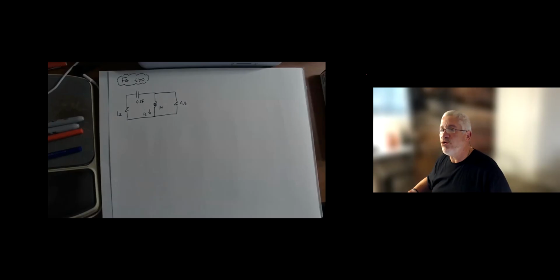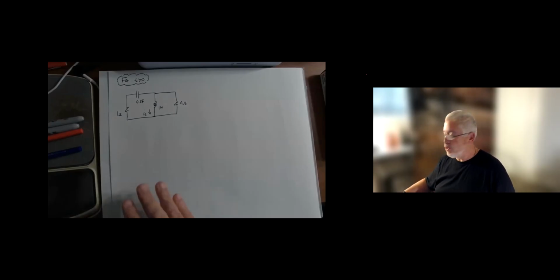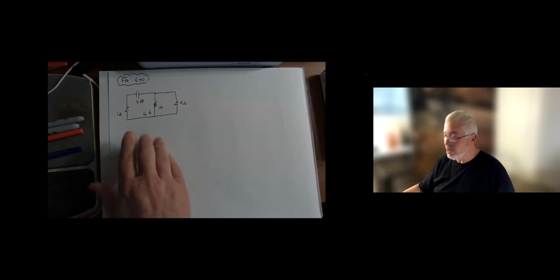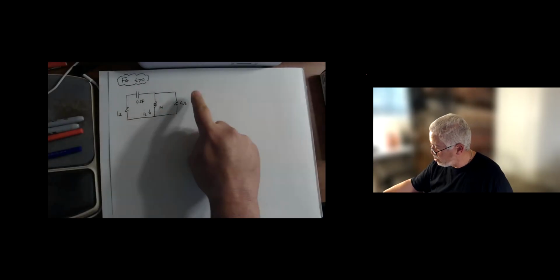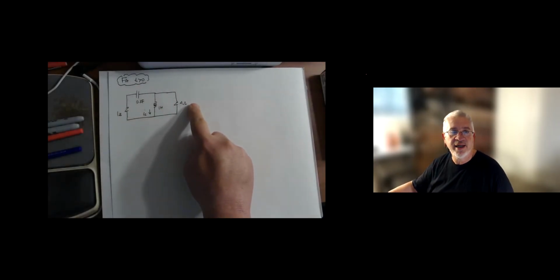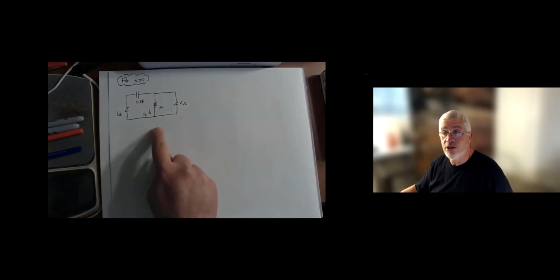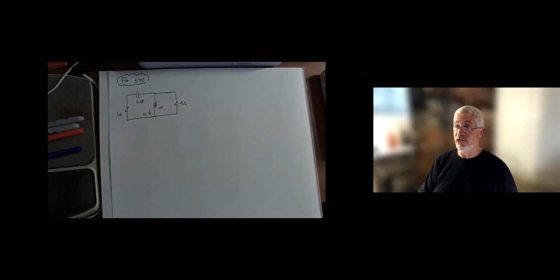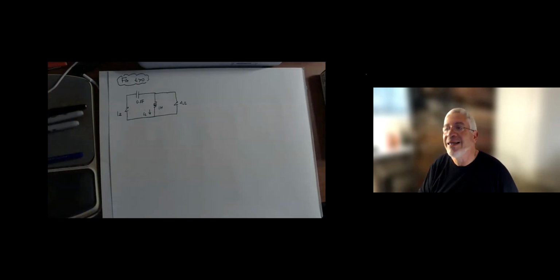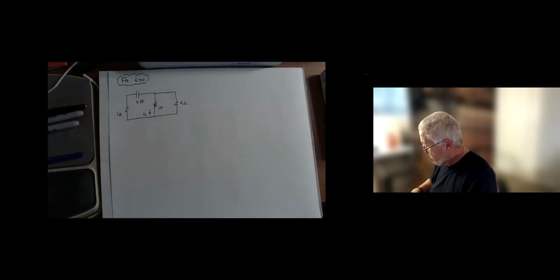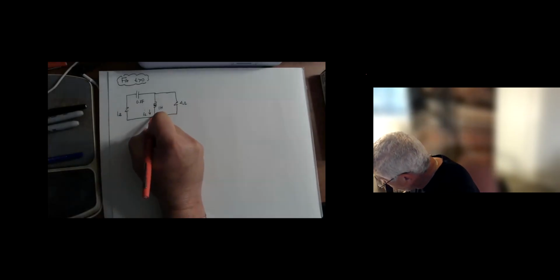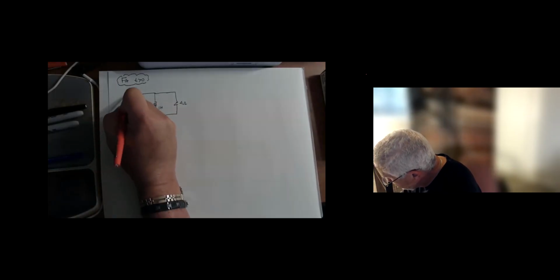But I would like you to see the nodal step-by-step procedure on how we get from this circuit, which is the circuit for t greater than 0, where the 1 amp source has been disconnected, and we have a circuit that has no source, but it has an initial condition. The initial condition is the capacitor voltage was 0 and the inductor current was 1 amp. So I'm going to proceed now and essentially begin my nodal procedure here. So I'm going to identify the nodes, and I'm going to use red for my nodes. And I have 3 nodes in this circuit here.